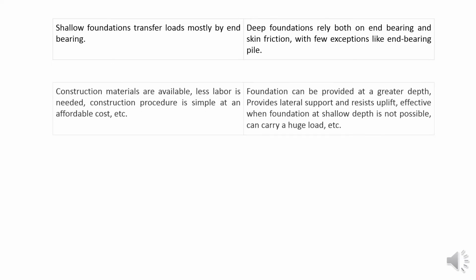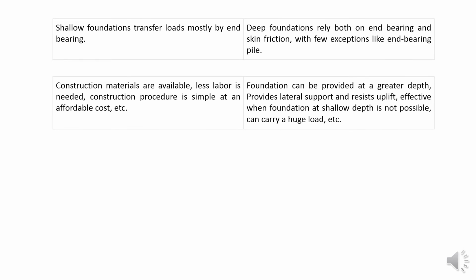Some of the advantages: in shallow foundation, construction material is available, less labor is needed, and the construction procedure is simple at an affordable cost. In a deep foundation, the foundation can be provided at a greater depth, provides lateral support and resists uplift. It is effective when a foundation at shallow depth is not possible, and can carry a huge load.